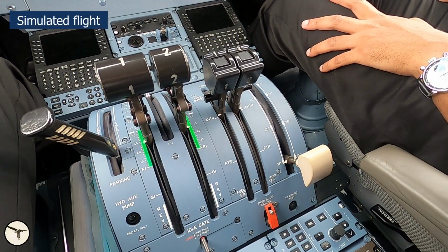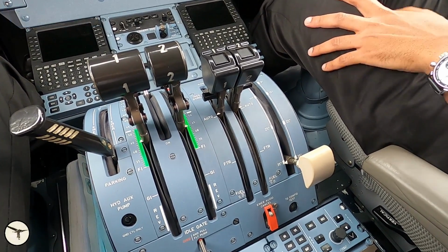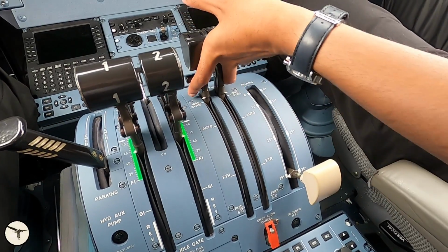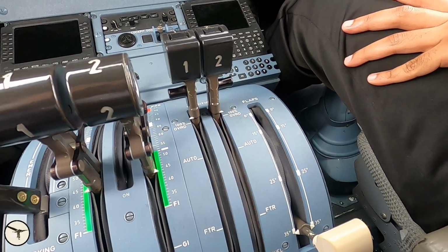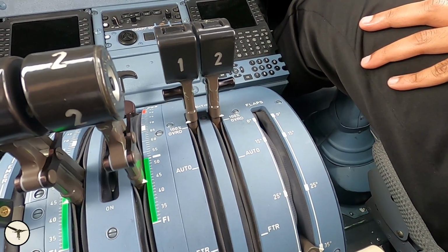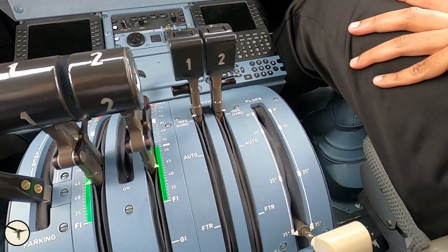Therefore, when we expect to encounter turbulence or wind shear during landing, we set the condition levers to 100% override. This position also works well as an air brake if we need to bleed off energy before we start approach.